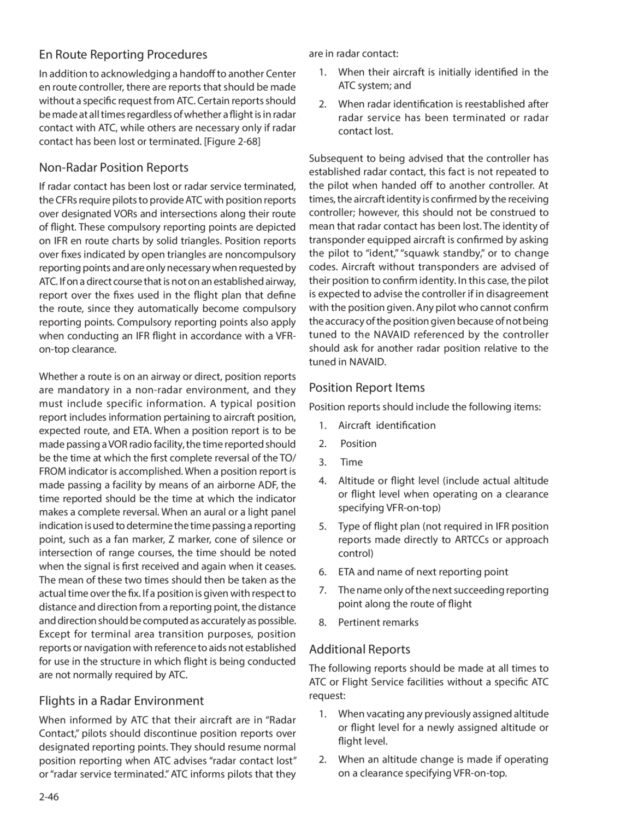Compulsory reporting points also apply when conducting an IFR flight in accordance with a VFR on-top clearance. Whether a route is on an airway or direct, position reports are mandatory in a non-radar environment, and they must include specific information. A typical position report includes information pertaining to aircraft position, expected route, and ETA. When a position report is to be made passing a VOR radio facility, the time reported should be the time at which the first complete reversal of the to/from indicator is accomplished.